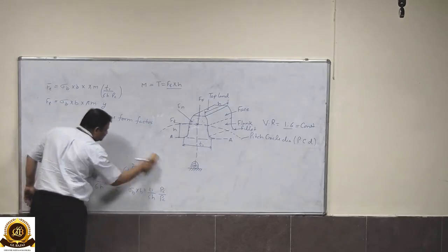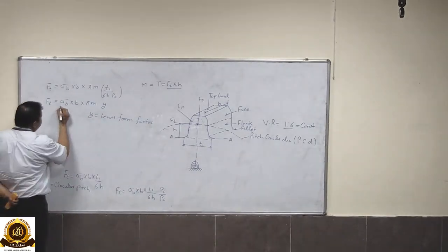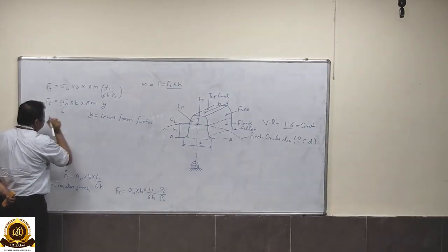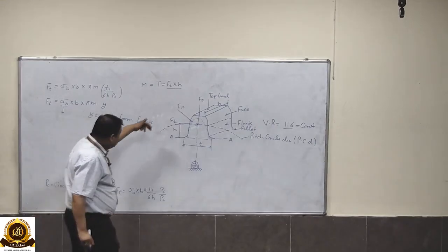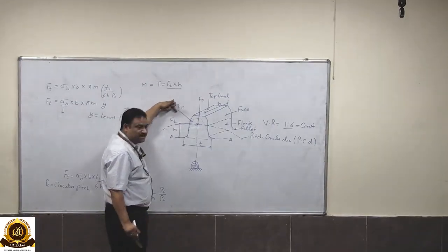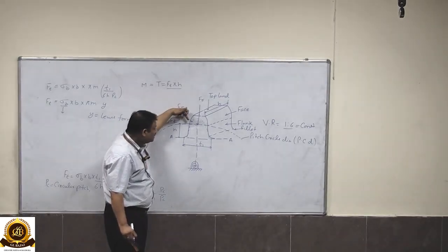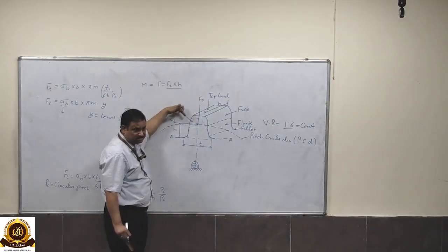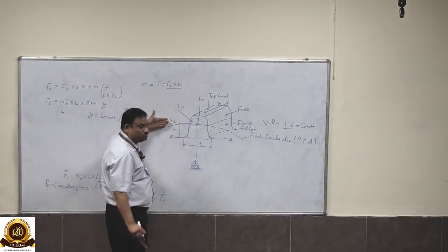So in this equation, further we can see that this sigma b is constant. But you can observe that during the engagement or disengagement, the normal force Fn will change in its magnitude and its direction. And its components are also not constant.